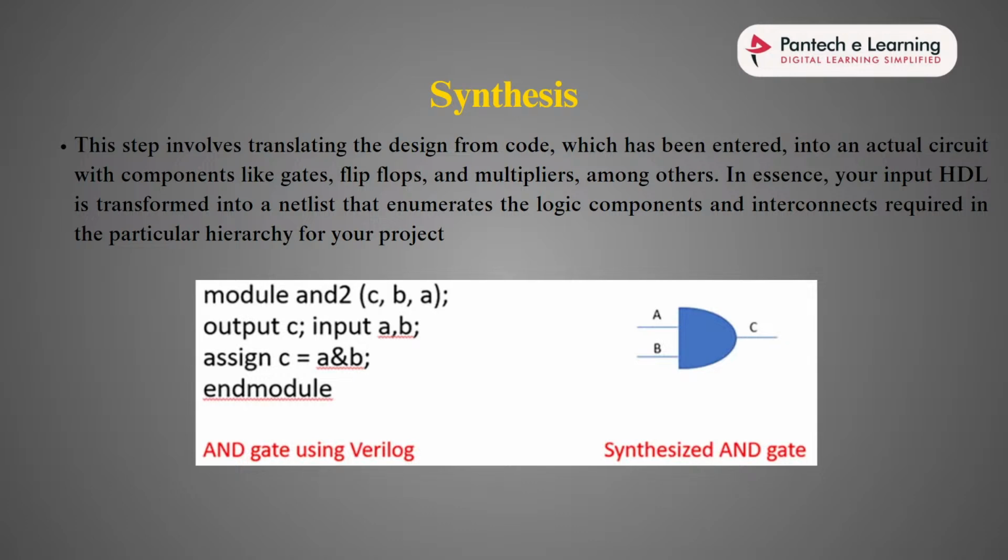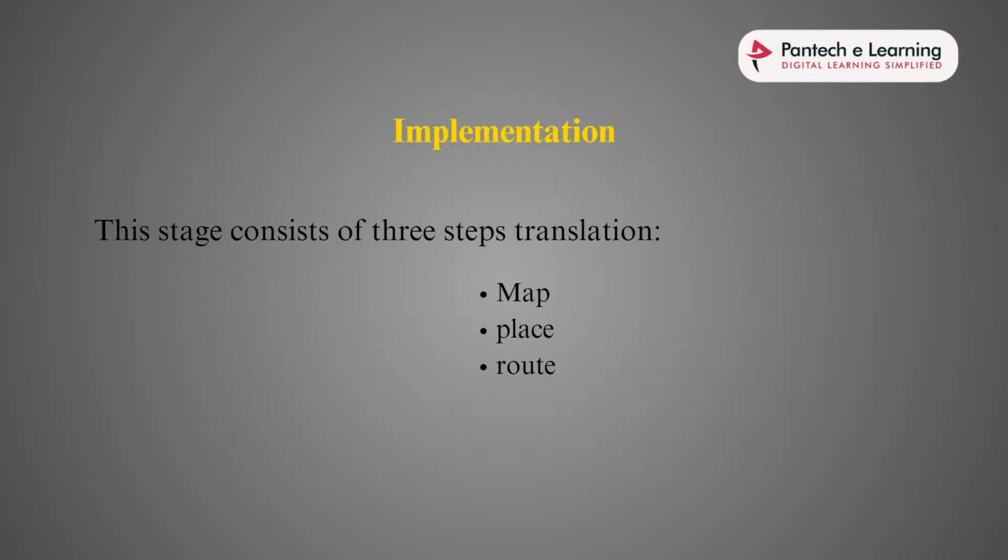In the synthesis stage, there is also a process like interconnection. Interconnection is about making connections between the logical elements, the logical gates, in the FPGA. We can't connect the logical elements by hand as humans. It is fully done by tools like Vivado and Intel Quartus Prime. It is made faster to implement by reducing logic, shrinking the design and overall size.